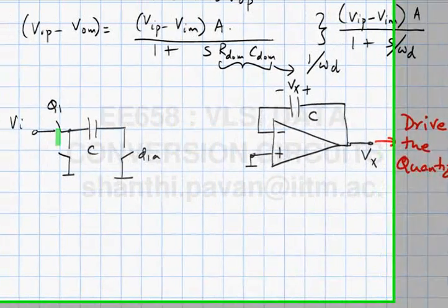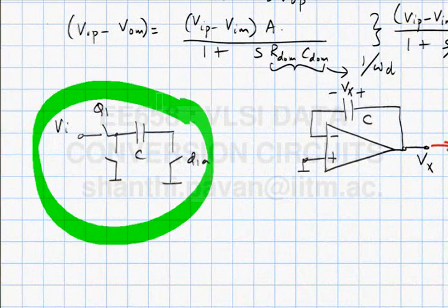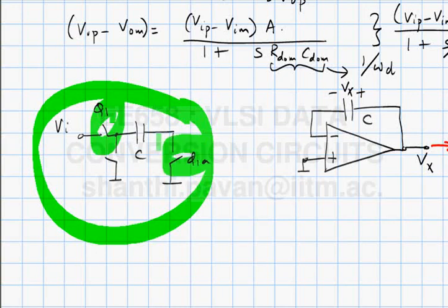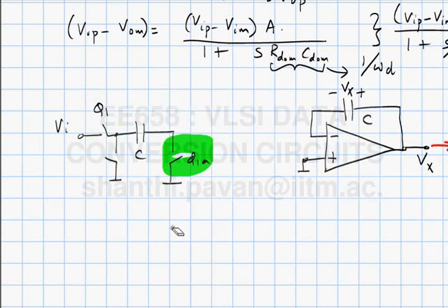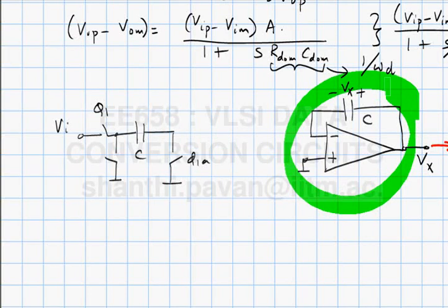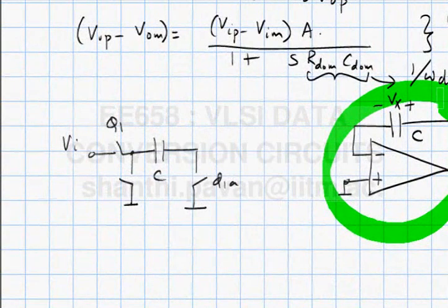One is you know how to sample the input onto a capacitor with reasonable amount of fidelity. For example, you would use a bootstrapped switch here, you would do bottom plate sampling, and so on. The moment you have sampled onto the capacitor, now you also know a way of making sure that whatever you do, the voltage on the capacitor is no longer corrupted and it in principle will be able to drive heavy loads that one might expect from a contraption that quantizes the output. So the next thing is to put these two things together in a single circuit.